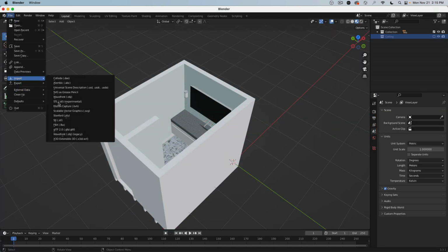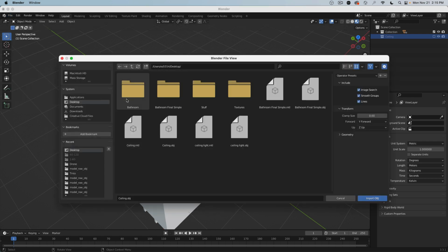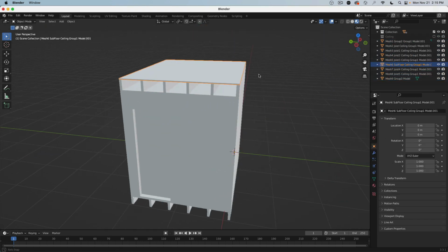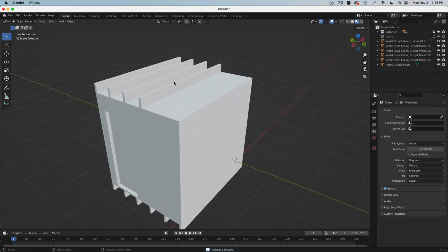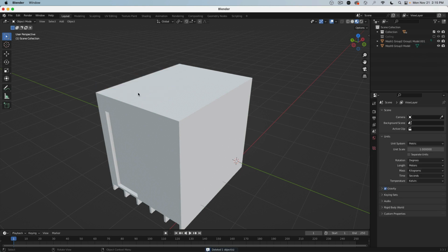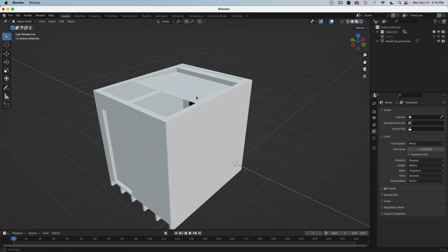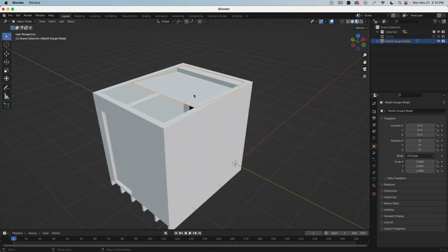So this basically means that when I go now back to Blender and import this new object, the whole ceiling actually came with it. So you saw it's not necessarily what is selected that's being brought over, but actually what is visible that is being brought over. So here I just simply deleted everything else. So there is my light. I can double click it and call this ceiling light, so I know what that is.